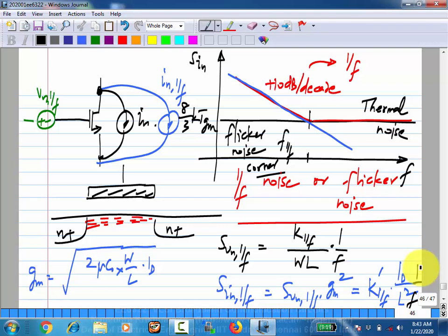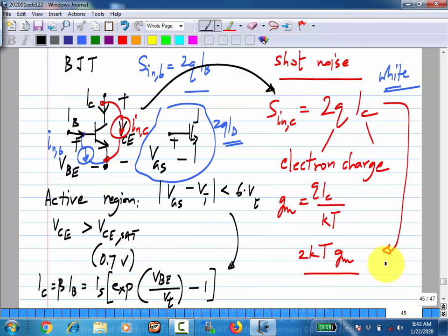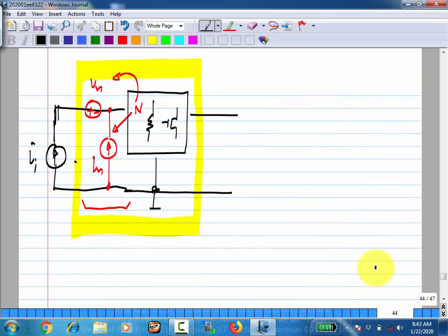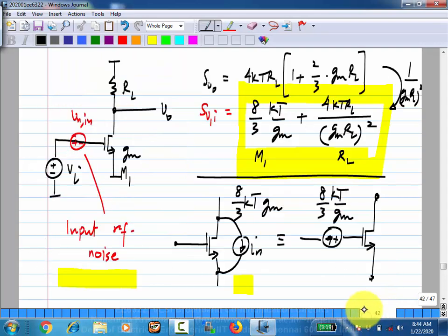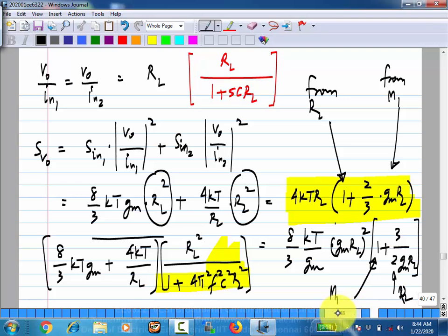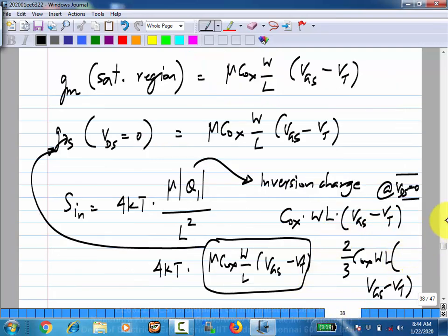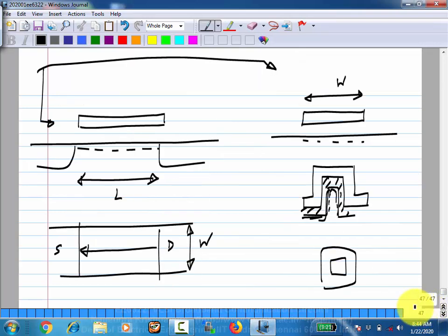This is fine. And along the way we also drew some conclusions, like if you have a capacitor C, you will end up with a noise of at least kT/C on it. Similarly, you can refer the noise to the input, and if you want to reduce the thermal noise in a circuit, essentially you have to increase the power dissipation. The noise scaling and so on I haven't dealt with; if we have time we will do that. And in case of a MOS transistor, you will also have flicker noise, which can be reduced essentially by making the device larger and larger.